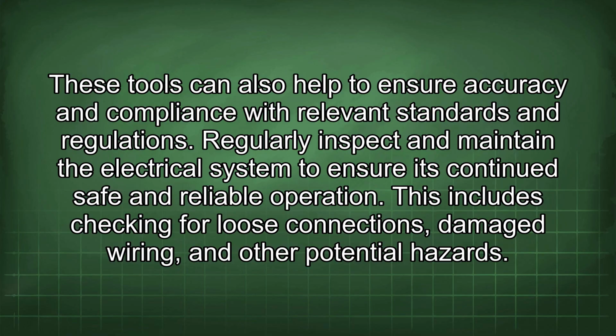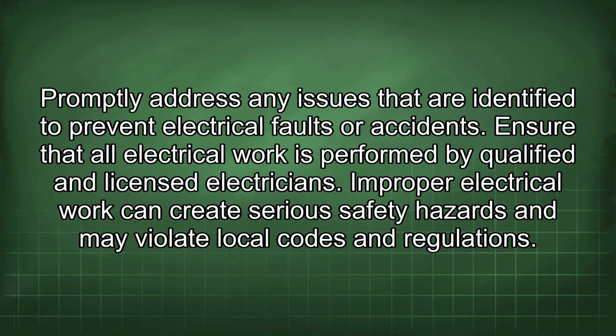Regularly inspect and maintain the electrical system to ensure its continued safe and reliable operation. This includes checking for loose connections, damaged wiring, and other potential hazards. Promptly address any issues that are identified to prevent electrical faults or accidents. Ensure that all electrical work is performed by qualified and licensed electricians.